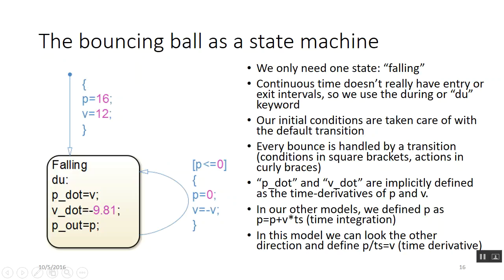Remember how we were talking about zero crossing and how previously we had to account for the fact that when we get to the wall, we're probably going to go past it, so we had to compensate back. Well, because it's a continuous state, the Simulink solver actually figures out when it's going to hit. It puts the solve point right there, and it reverses it, and it's pretty cool.